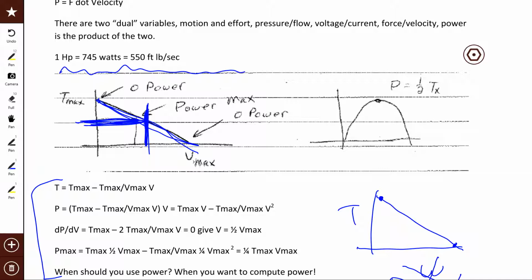Right? So if you have an inefficiency in the car, you're going to deliver the power from the engine. Some of that power is going to be wasted in the losses, and what you're left with is force times velocity that will drive you up the hill. That's what's left over. You've got to have the F or you won't go up the hill. So the motor will slow down, right? According to the curve, the motor will slow down until it gets the force that you need. And when it gets the force that you need, whatever that speed is, that's the speed you're going to go up the hill. Does that make sense?